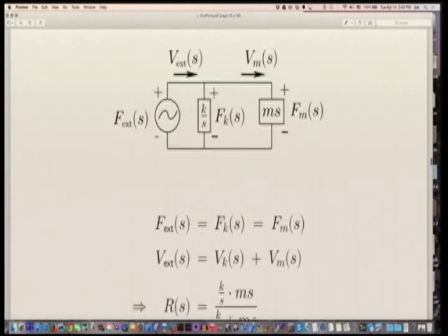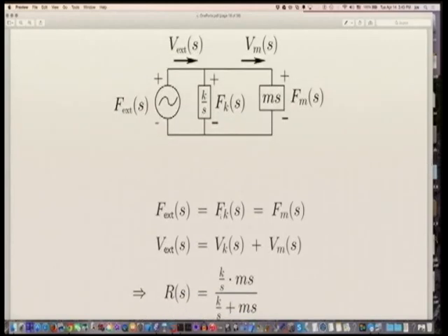Just kind of say that in again? Yeah. Maybe something that we haven't covered about ports is that when two ports are connected, they have to have the same port impedance by definition, or otherwise there's scattering that occurs.